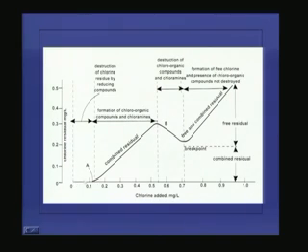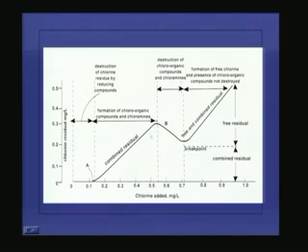After some time, when all those things are destroyed, ammonia is present in the system. Monochloramine, dichloramine, and trichloramine will all form in a stepwise manner. The residual chlorine will be a sum of HOCl, OCl-, monochloramine, dichloramine, and trichloramine. You will get a curve something like this. And at this point B, all the ammonia present in the water has already been converted to trichloramine, that means NCl3.